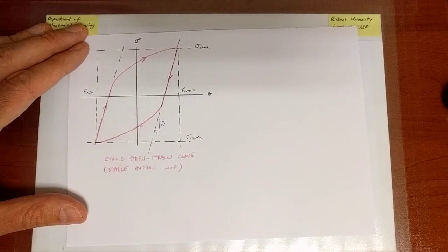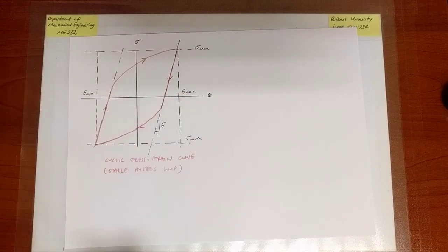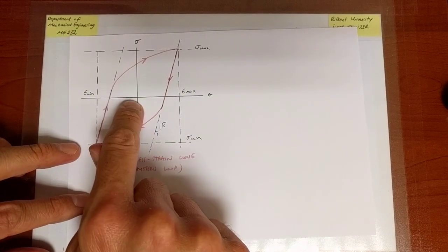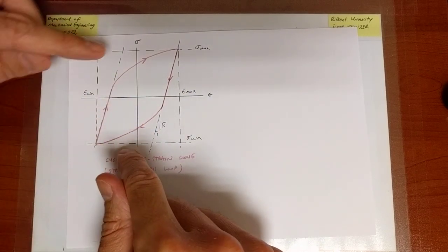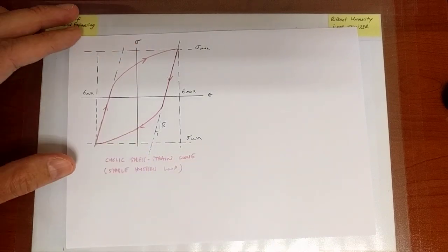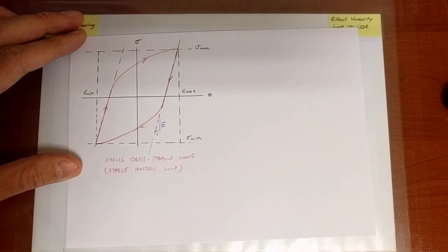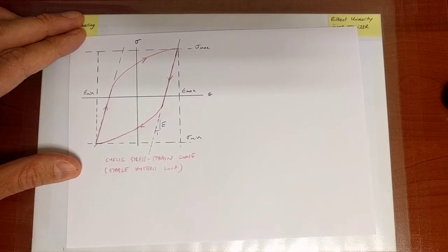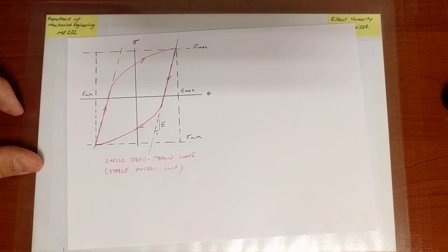or the stable cyclic stress strain curve. Eventually we understand that this is the behavior that emerges after many cycles of loading and unloading between a max strain and a mean strain. Again, zero mean strain we are assuming corresponds to zero mean stress. So now let us try to interpret some of the quantities that we are seeing in this plot.